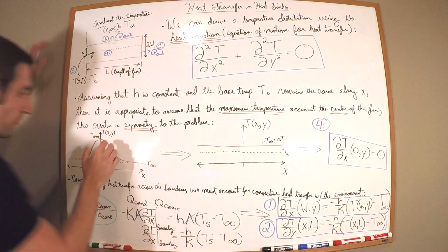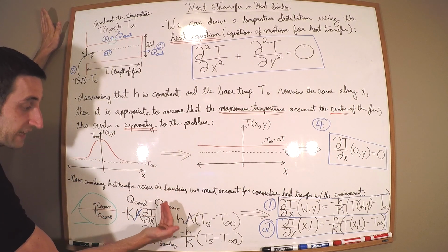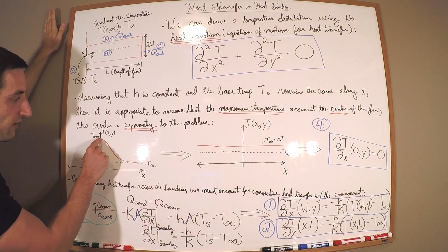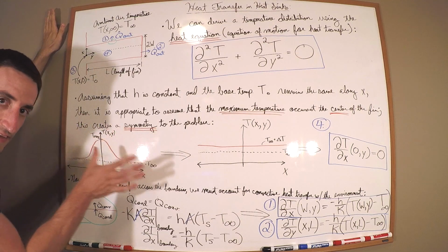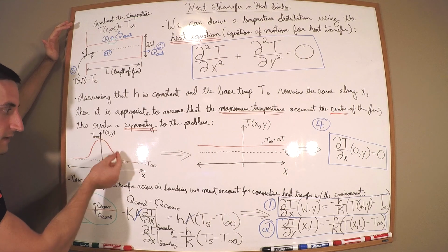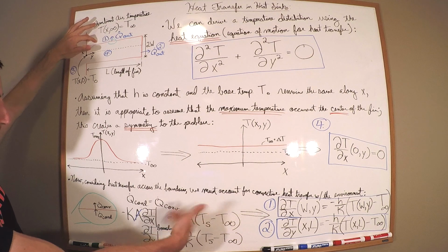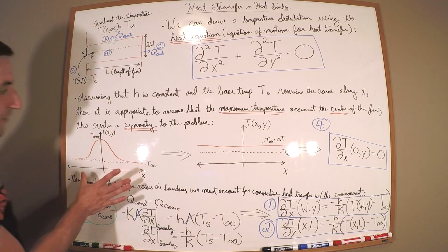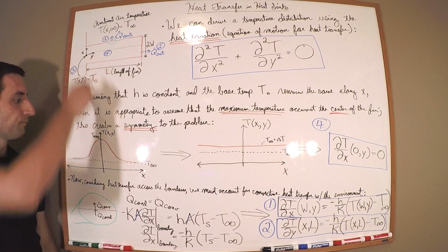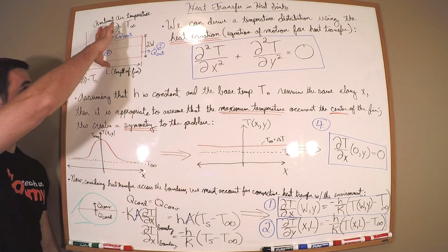So, the maximum temperature, what we see here, I'm going to go down here. Conduction is negative kA times the derivative dT/dx, right? So if we have a derivative, that's going to signify heat transfer. So initially, it wants to go down here, so we need some curvature. And then we're going to have a different curvature for the convection, which is going to be dictated by the convective heat transfer. And that creates a temperature distribution as follows, where this is x equals 0, right in the center. It has to drop off to drive heat through these surfaces here.